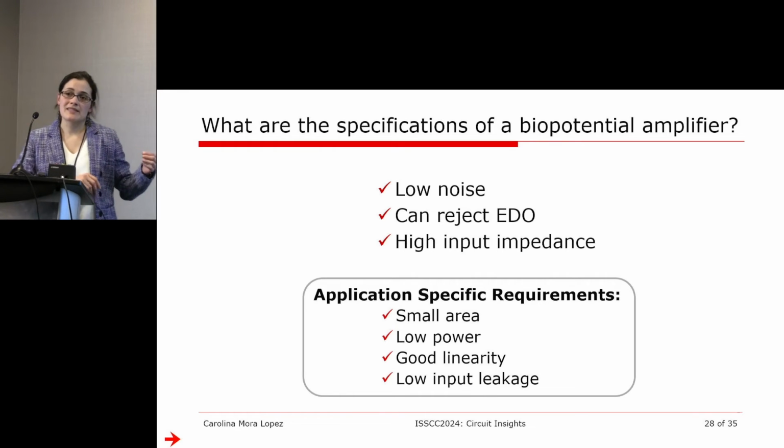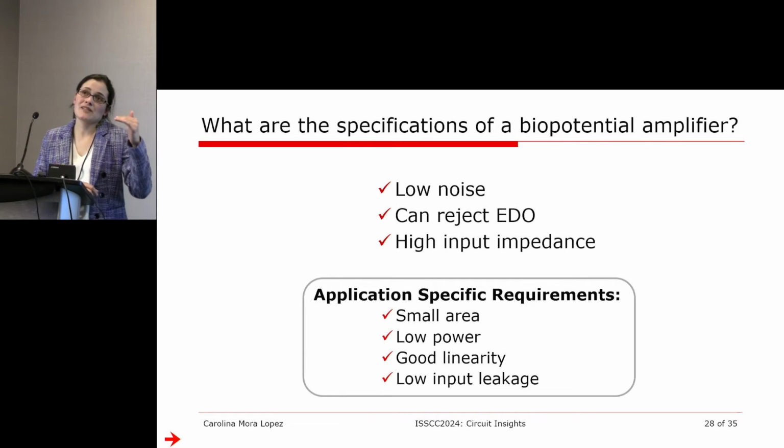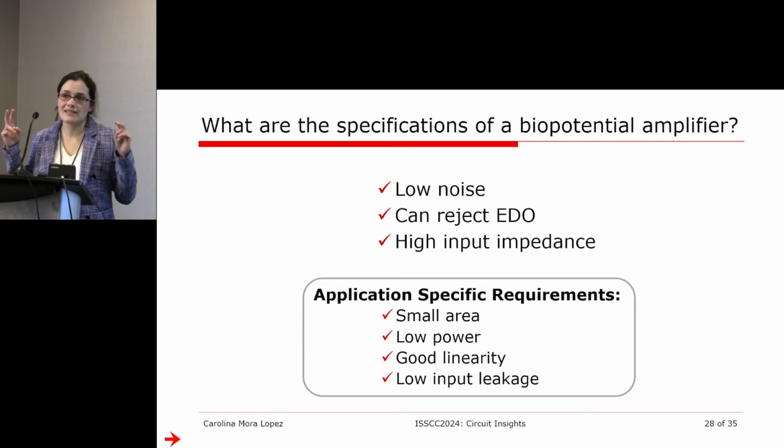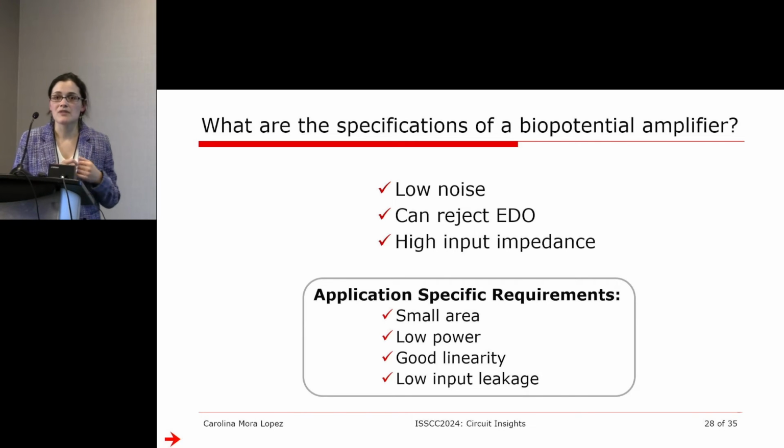And with BJTs, the difference from CMOS is that you do have an input current that makes part of your transistor operation. So in CMOS it is actually ideal that your input current is almost zero, but of course you still have leakages in smaller nodes, but this current at the input is not tolerable in many applications.